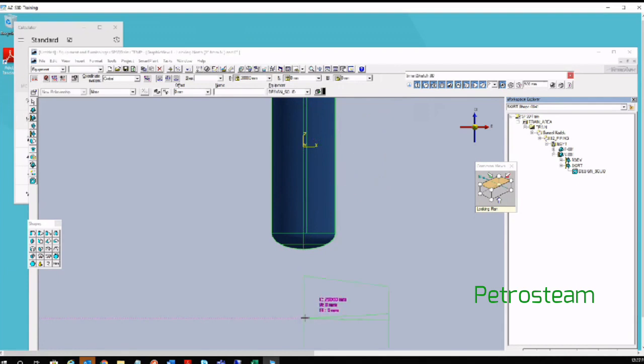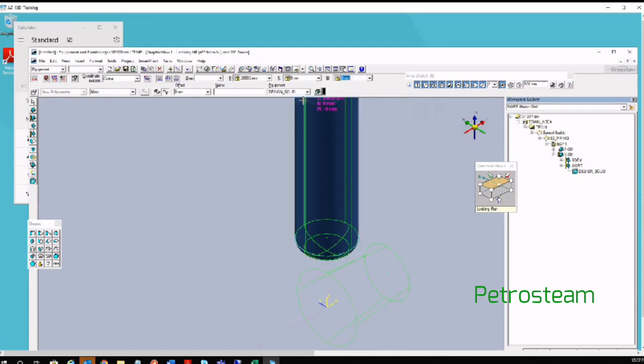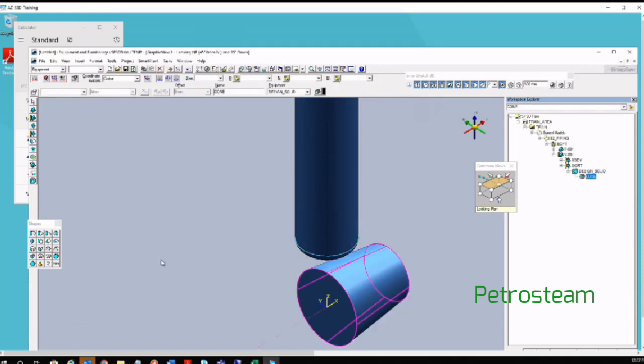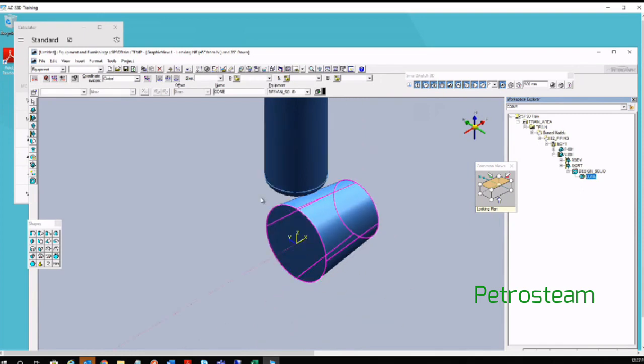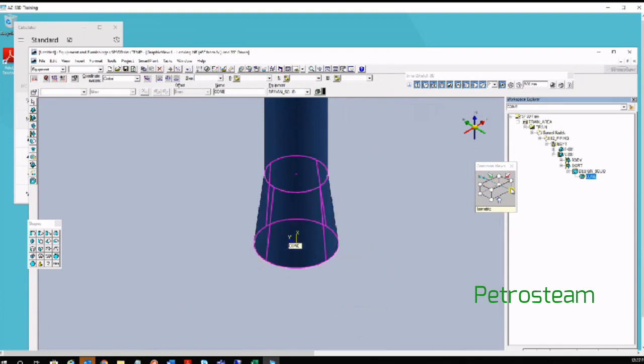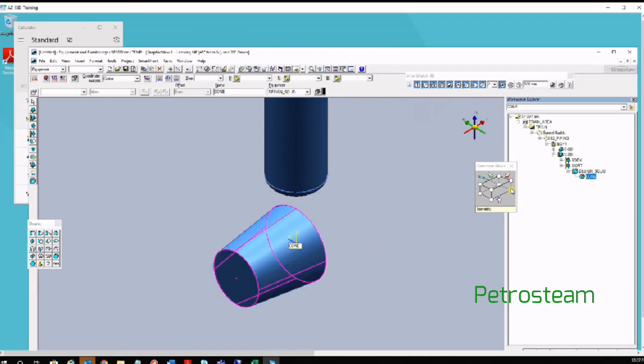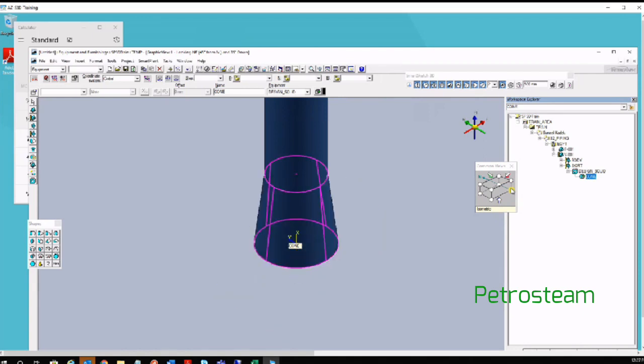Okay, exactly at the bottom of this cylinder we have placed. So I have fixed the location for this and then complete this shape. Already the cylinder is selected and the y-axis is active. Similar to earlier, you have to use the right arrow mark to rotate the cone you have placed. Okay, all of you clear? I have placed the cone now.